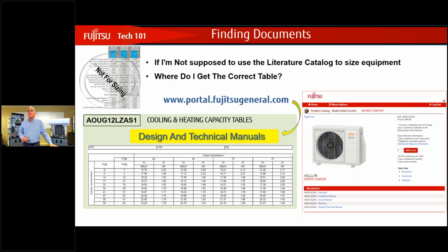When it comes to minimum line sets, if you are short on your minimum line set, can you do both a vertical and horizontal loop? Oh, great question. There's only one loop we want: horizontal. If we do a vertical loop, we create a trap. So we never want to create a trap. When we go up to 5-story, 6-story, 8-story buildings, and we tell you 98 feet, that's what gets us into that. There's no trapping needed.